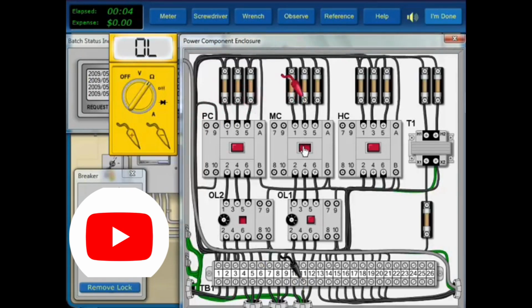We read infinite resistance. This means that the open is within the control box. We split this area in 2 at the bottom of the contactor. The low resistance reading tells us the open is above the test point. Testing at the top of the contactor with it closed indicates the contact is okay. Now, the only possible causes are one wire and its connections.